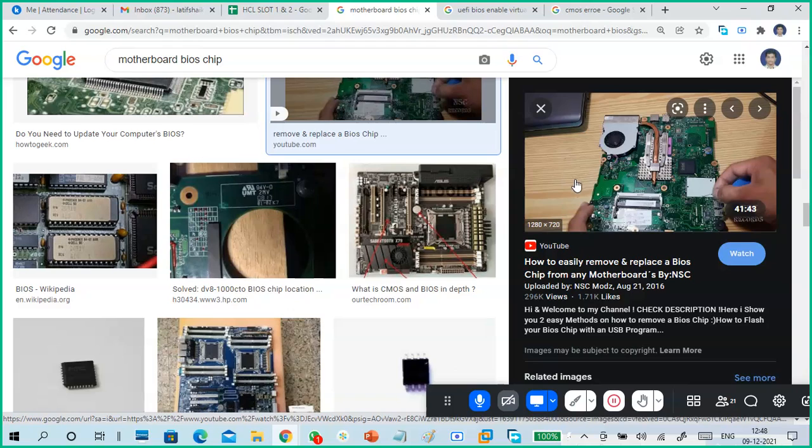Don't put any cloth kind of stuff under it. If you put it on a bed, the bed sheet contains a lot of dust particles. Even if it is a new cloth, the cloth blocks the area, so heat won't escape. The heat will go inside your laptop. Guys, this is another important thing.